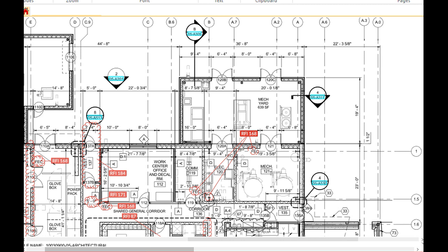There's typical conflict between architectural and structural plans. Upon checking the plan, you notice that the size of one column is different in the architectural plan and in the structural plan. For structure, the structural drawings and notes always override anything on the architectural drawings.